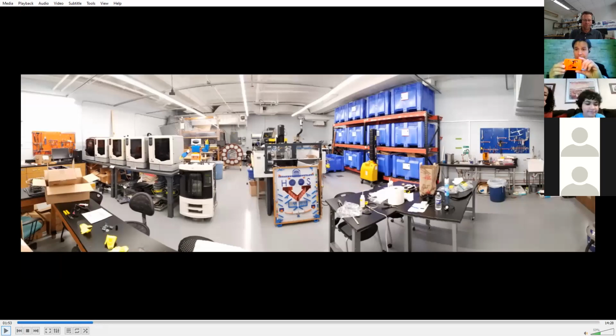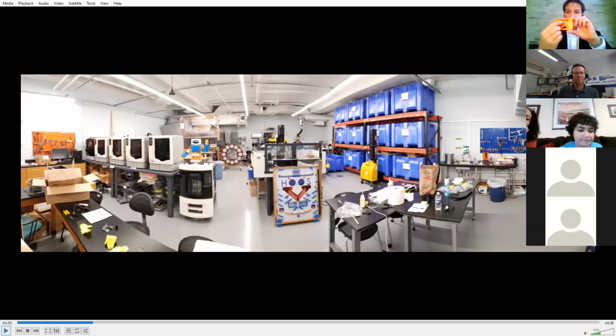This is a Geneva drive that all comes out of the machine fully assembled because it has a dissolvable material that's in the air gaps. It just comes out of the printer with the cocoon of this white material. You dip it in a bath of sodium hydroxide for a couple minutes, and you take it out, and it's fully assembled and ready to go. So you'll see that I incorporated that into making these kits this semester as well, these fleets of 3D printers.